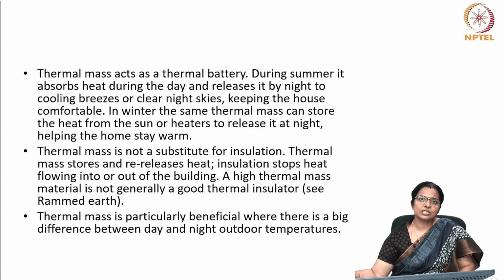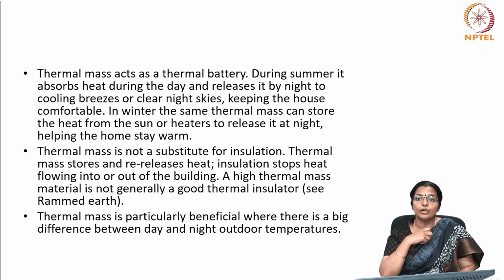Thermal mass is not a substitute for insulation. Thermal mass stores and releases heat, and it depends on the material that we are talking of. Insulation stops heat flowing into or out of the building. A high thermal mass material is not generally a good thermal insulator. For example, rammed earth.